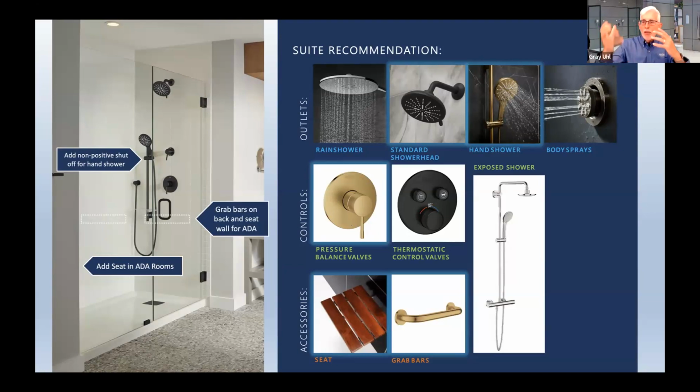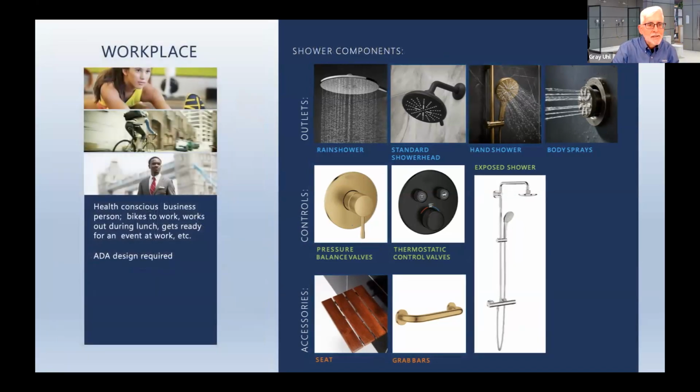And they're all the things I talked about today: placement of the controls, placement of the glass door, accessibility, and it's really becoming common to see not only a standard shower head, but an adjustable slide bar and a handheld in a hotel shower. As I shared with you before, and this has to do with cost, almost all hotel showers have a pressure balance valve as opposed to a thermostatic.